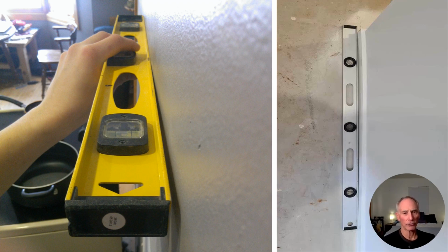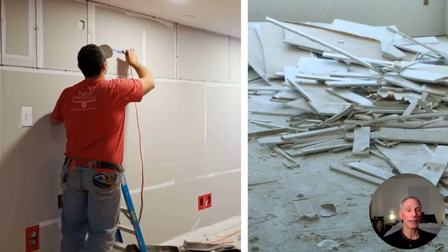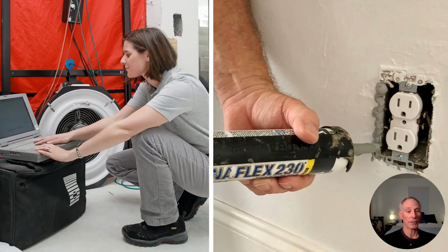And finally, when you go inside the home and look at the details, in conventional construction, we know we're dealing with tremendous challenges with dimensional accuracy. We know that framing tends to move and expand and contract much more, so you're vulnerable to cracking. We also know that sheetrock or drywall has to be installed directly on a stud, so there's a tremendous amount of cutting and fitting, and therefore also a lot of waste that has to then be transported to the dumpster bins. We know that you have a lot more challenges when you have blower door tests meeting the targeted air tightness levels, and often a lot more rework to air seal when you have to bump up your numbers you're getting from the testing.